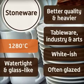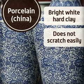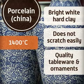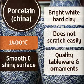Porcelain or china clay is a bright white and harder clay that does not scratch easily. It is used to make porcelain for quality tableware and ornaments. It is fired at a higher temperature of 1400 degrees Celsius, and the resulting item can be translucent or opaque depending on the makeup of the clay used. Once the porcelain has been fired, it's tough and has a smooth, shiny surface. Porcelain is difficult to handle and is therefore used mainly by experienced potters.